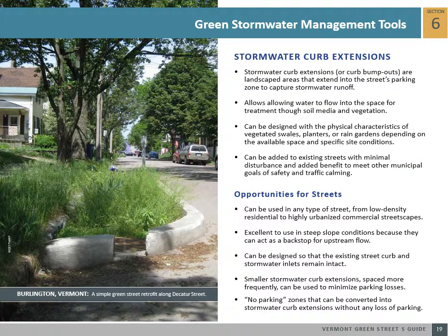Stormwater curb extensions have many active transportation, urban ecology, and neighborhood enhancement benefits. They can narrow intersection crossing distances, slow traffic, and create a safer and more walkable environment. They can provide additional stormwater storage and flow reduction, as well as pollutant filtration, which helps prevent damage to downstream water bodies. They can significantly help with placemaking and provide community public space.